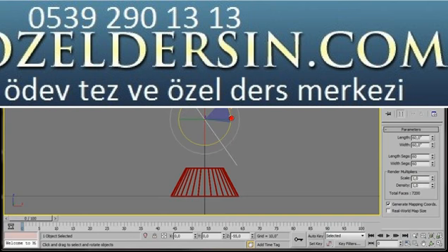There, just watch the dial as you're turning. Okay. When it's 50 degrees, we'll select the Move tool and we're going to drag it up. Now it's very important that you place it in the same position as I have in this video. It usually takes a lot of trial and error to find the right position for the plane. Just type in at the bottom of the screen in the x-axis minus or negative 8.528, y 0, and in the z type in 46.5.